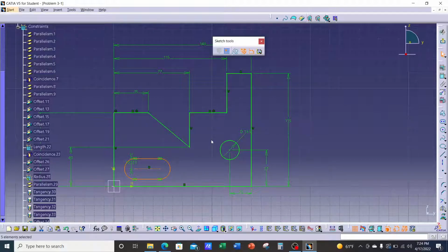And as I mentioned before, I want you to notice that in the sketch tools, these are orange. So because these are orange, these are on. When these are on, it's creating constraints. So if we go back to the slot, it created tangencies. As you can see, you have 4 tangencies, the arcs and the lines. And there's also that horizontal. And there's also an offset to represent our radius. So this is the offset. Okay, so let me first click out in space to deselect, and let's go ahead and add those 20/20 dimensions.